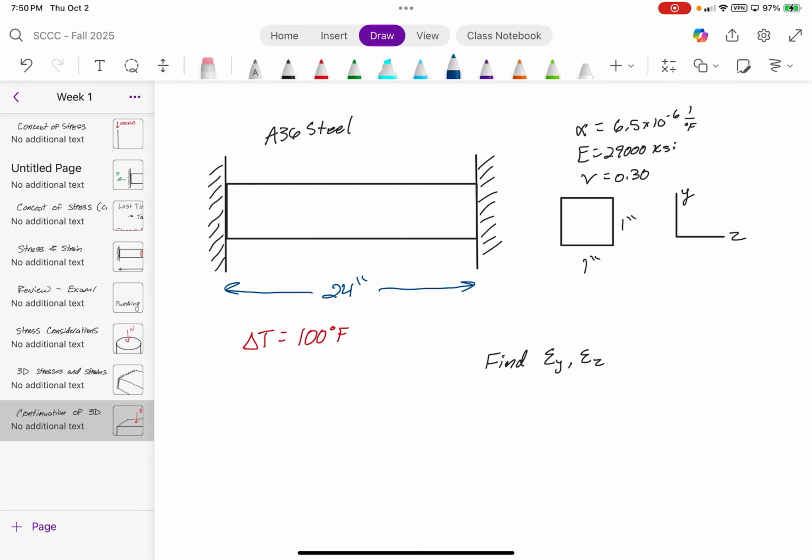The unknown would be your reaction, but you now have delta equal to PL over EA, where P is the only unknown. Does that make sense? Write out your deformation due to a force being applied on the structure. Do you remember that? It's NL over EA. P and N are the same thing. P is just a general force, N is like the internal. For this one, it's a singular bar, but it would just be whatever the total deformation is due to the force change.